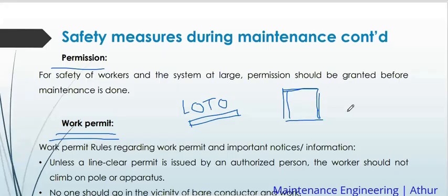Otherwise, someone may call and complain that the whole power is off, then another person comes and puts it on. But when you find a tag out, you have to put a tag that this line is under maintenance. That is tag out. Very, very important to note.